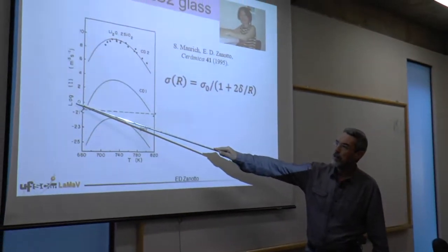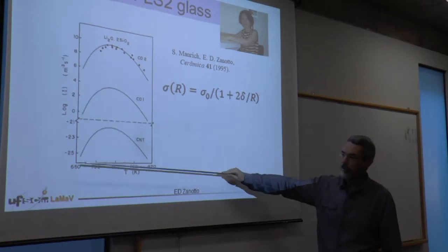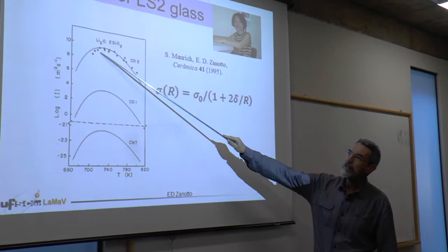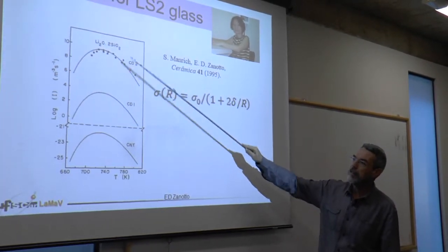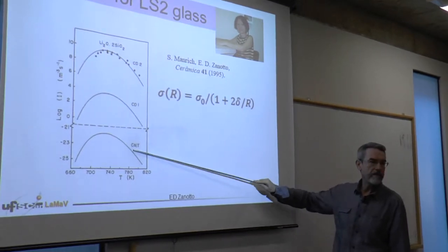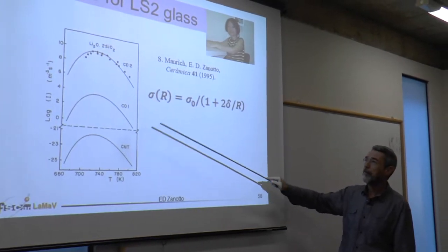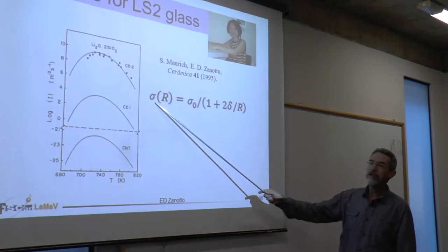when one uses a constant value of the crystal-liquid surface energy and the viscosity for the transport part. However, it does describe the temperature dependence of the overall nucleation rates as a function of the temperature. It can describe, as we can see in this graph here, the log of the steady state nucleation rates versus temperature, experimental data, here the black dots for lithium disilicate glass, and the predictions of the classical nucleation theory. One way to avert this problem is to then assume that the surface energy is no longer constant,